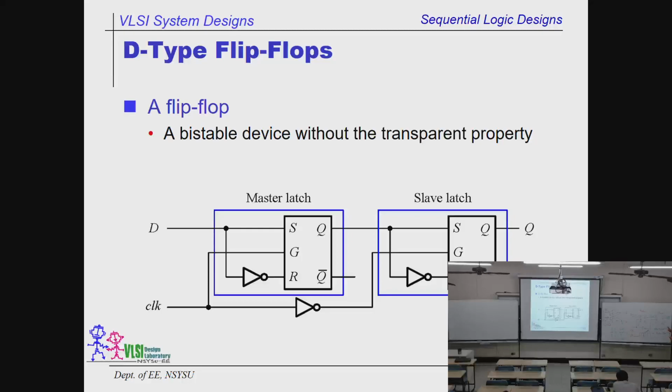If I want to do the rising edge, how are we supposed to do that? It's easy. If you want to do the rising edge, you simply move this inverter over here, and it'll become the rising edge. That's it. No surprise.